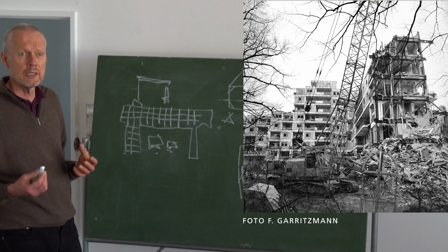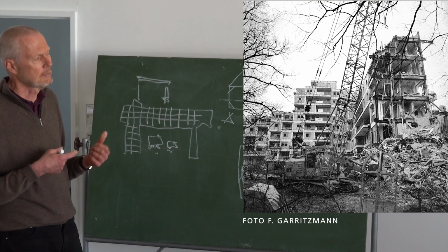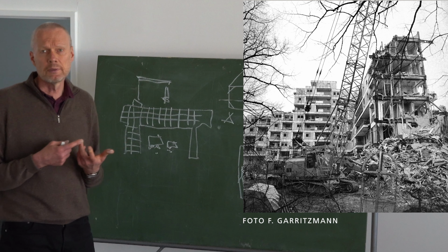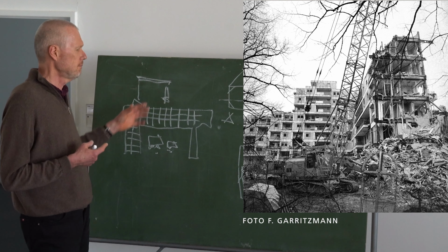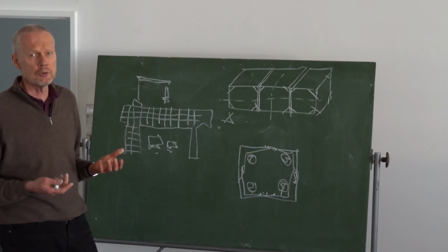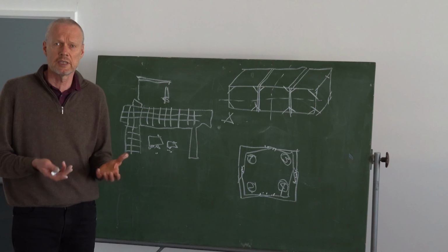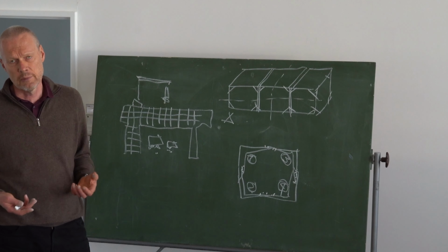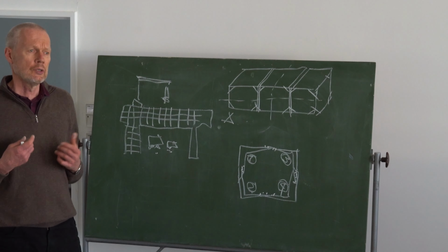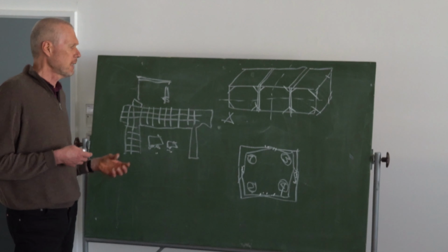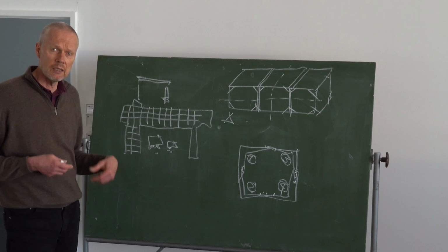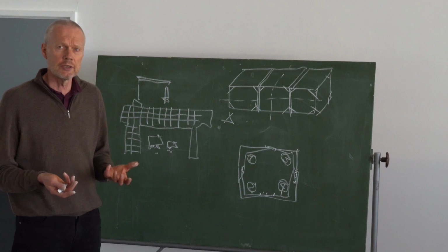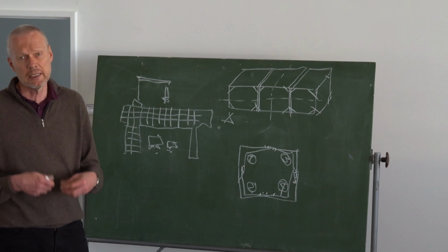It was demolished because there was little maintenance, and there were some thermal bridges as well, and people didn't really want to live in this. And at the construction it had been 20% more costly than comparable housing projects were. So in fact, a couple of disadvantages, and you can see that the idea of mass producing the same elements is not sufficient to guarantee low prices as an outcome.